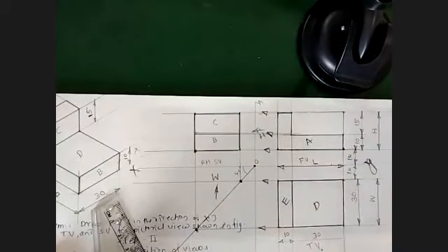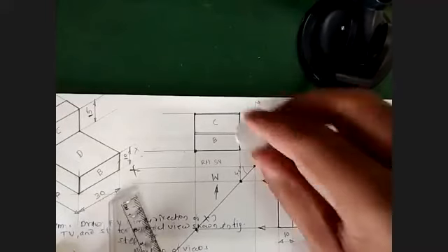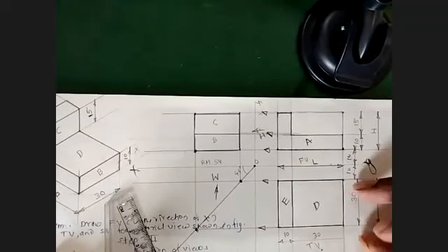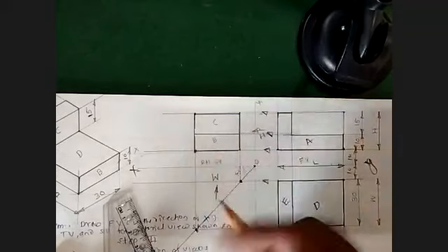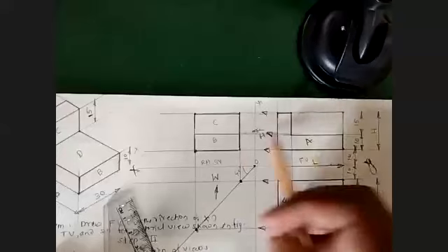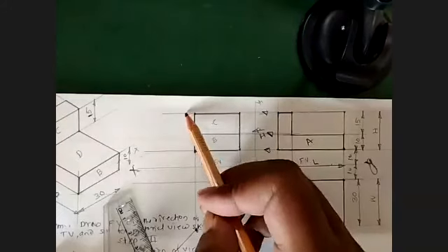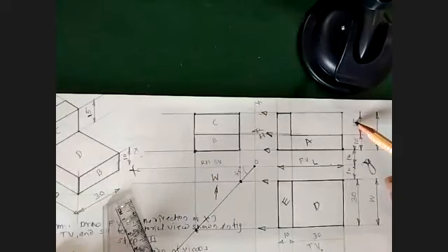So this is the way to give the dimensions. Now for side view, you need not give any dimensions in side view. Remember, you need not give any dimensions as far as this case is concerned. Sometimes you can use certain dimensions in side view. See, the width is given as 30, same it is. Height already, if you look for C, if you mention 15 here, 10 here, not required, because it is already given in front view and it is clearly showing that this 15 is nothing but this 15 as well.